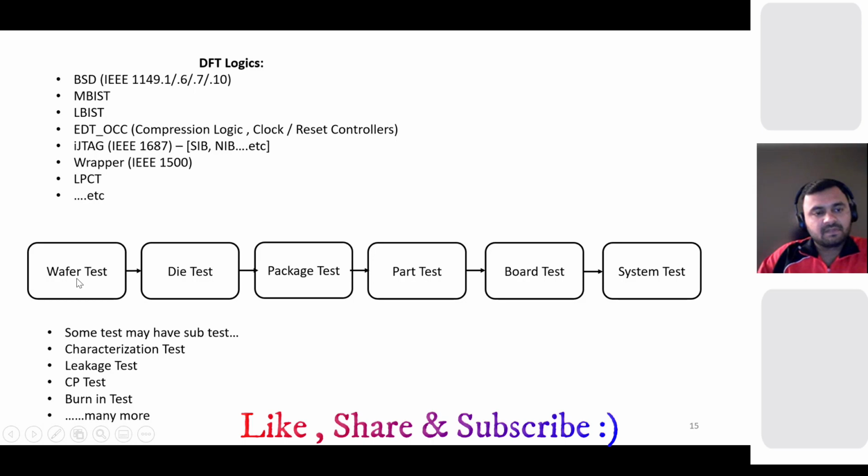And we do wafer testing. As you saw in the previous slide, we do the wafer test, then we slice it, we do the die test, then we package it, we do the package test, then part test, board test, and system test. So many tests happen. Each of these tests may have sub-tests, like characterization test, leakage test, chip probe test, burn-in test, and many more. In burn-in, you test your chip under extreme conditions, like extremely high and low temperatures, and extremely high and low frequencies. That is called burn-in test. These are the basic introduction of the digital logic, what we do.